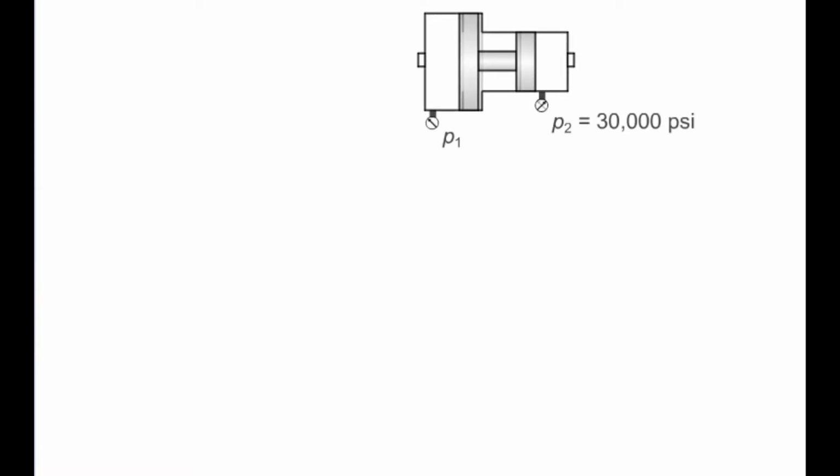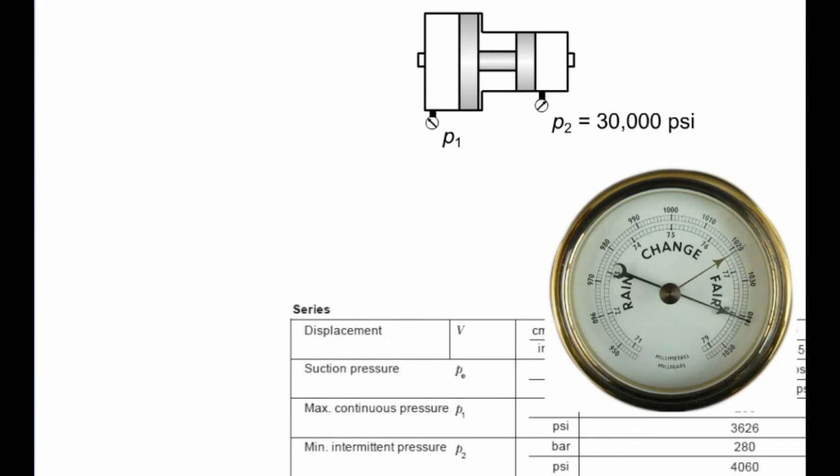Pressure in psi is very frequently encountered as a measure of pressure in the imperial system, not only in this module but in hydraulics generally as well as in everyday life. We need to understand what 1 psi actually means and how it relates to other units. PSI is actually an acronym for the unit pounds per square inch and is the pressure which is generated when a force or weight of 1 pound acts on a surface area of 1 square inch.